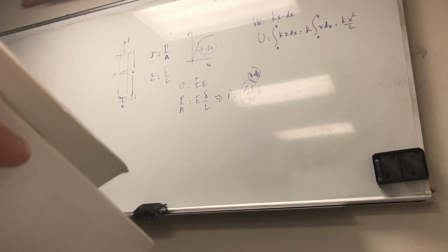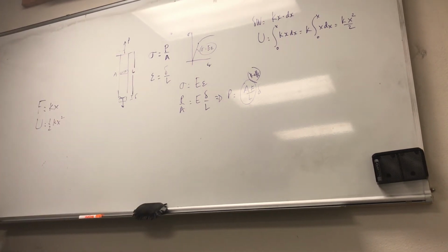There are two moments of inertia that I know. It's the mass moment of inertia, isn't it? Now, you only use the mass moment of inertia for dynamics. For beams, remember the flexure equation? I is the area moment of inertia. Right, it's an area property, right? Remember BH cubed over 12, if that rings a bell?